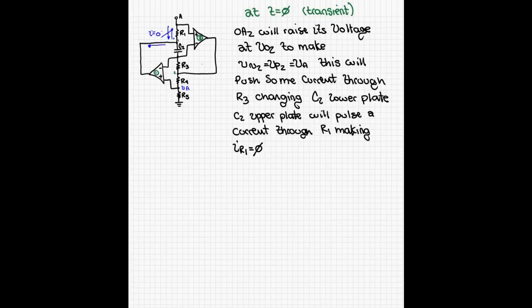Basically what we have is the same component right here, which is going to have IL equal to 0 and VL equal to VA. Correct. So that's right for an inductor. As soon as you close that switch, it's going to resist the change in current. So IL is going to be equal to 0, but the voltage drop can change instantly. So we're going to see it right there.